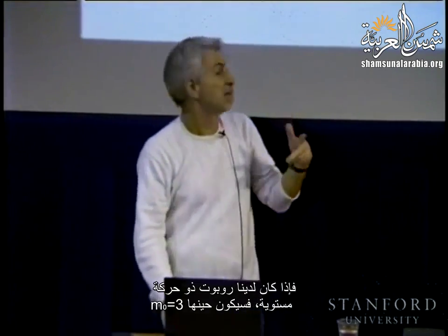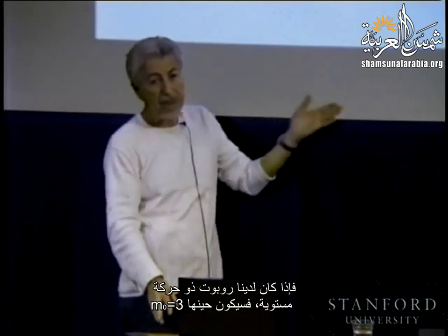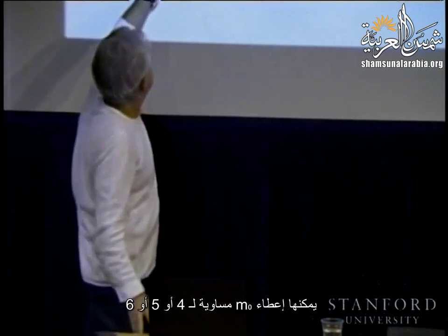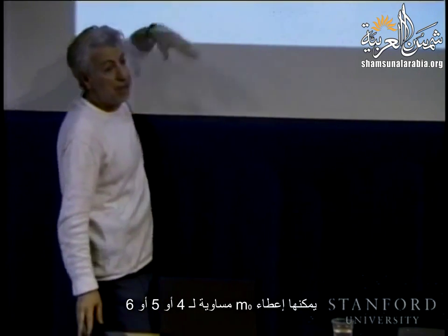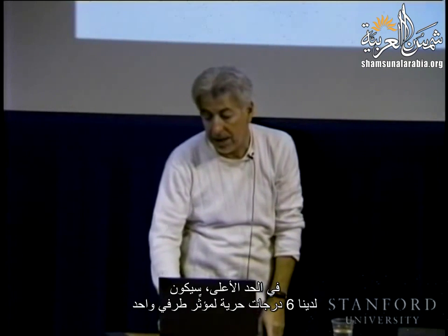And for the orientation, 1, only 1. So 3. So if we have a planar robot, then we will be talking about m0 equal 3. And you have different robots with different characteristics that end up giving you m0 equal to 4 or 5 or 6. But at most you have 6 for one end effector.